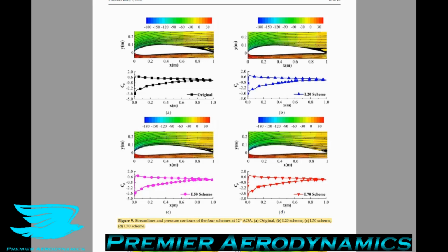So when the riblets are arranged at the airfoil surface, the trailing separation vortex of the 3 configurations are significantly reduced. However, the enlarged leading separation vortex are also induced by these riblets. So on the one hand, you're getting rid of one vortex. On the other hand, you're increasing the other vortex. Now, whether the strengths of these vortices are growing or shrinking, you can't really tell just from streamlines. You need to figure out what the vorticity is, then integrate that over a closed line integral, and then you can figure it out from there. So we may assume that just because the vortex is bigger, it's stronger, but that's not necessarily the case.